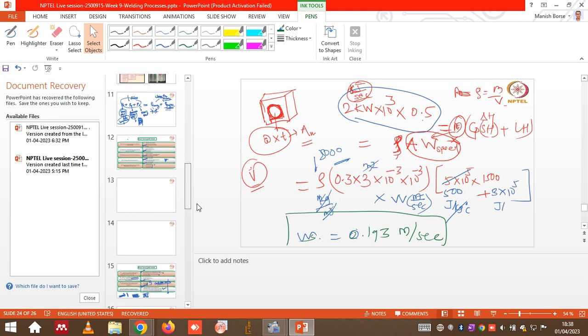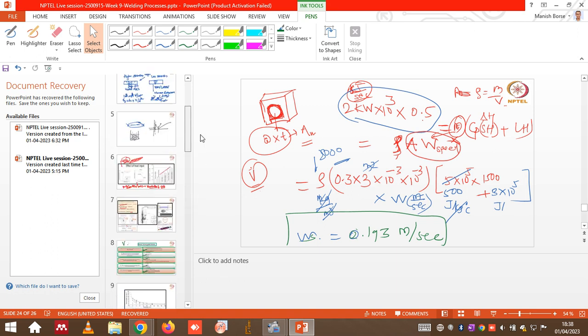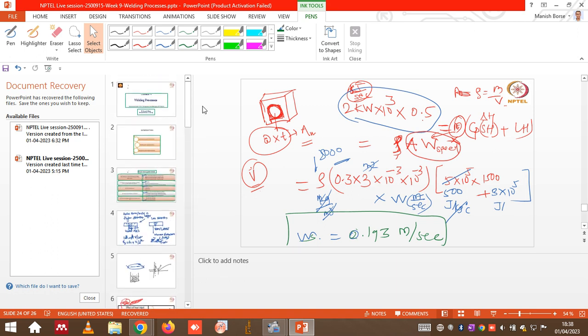Okay, maybe we can cover the topic you mentioned regarding solidification cracking probably in the last live session, and discuss it again in more detail, including the different regions. That's the only region I mentioned about wrought alloy, but there are other regions, like low melting eutectic phases present at the grain boundary area.